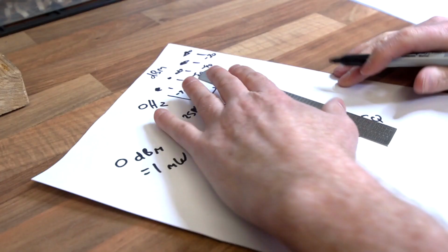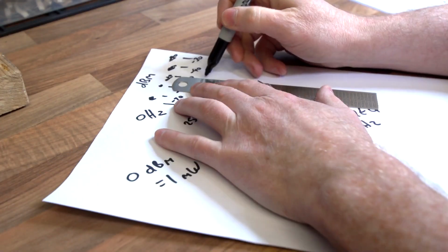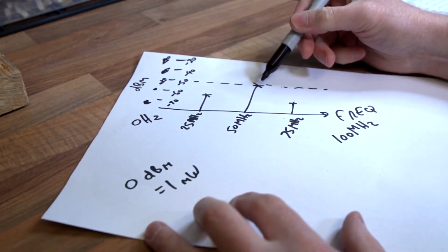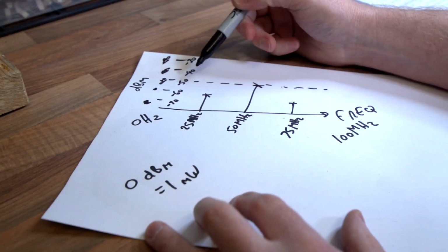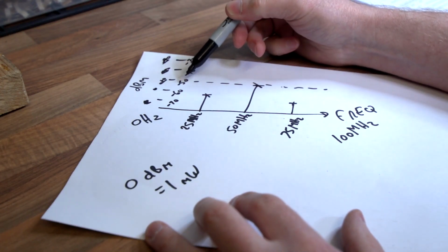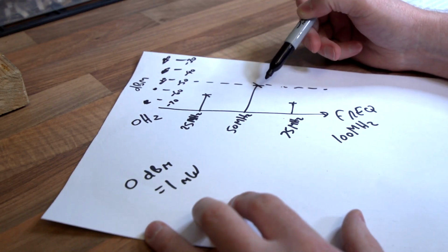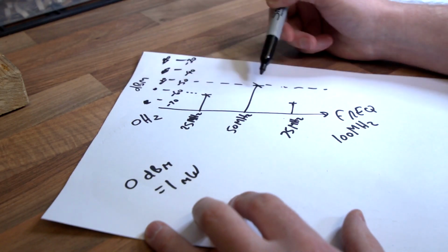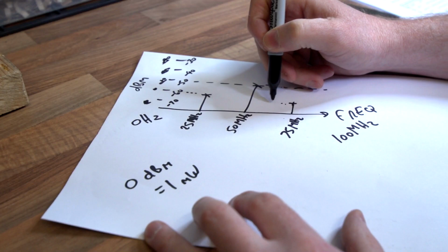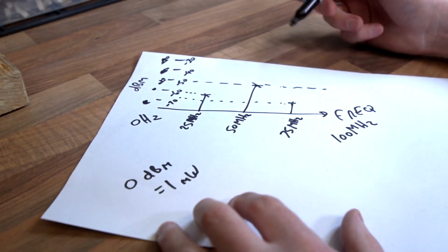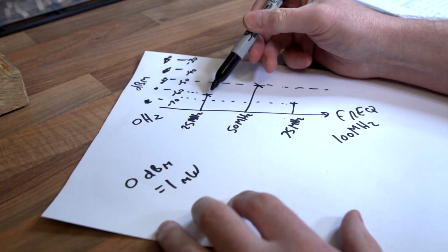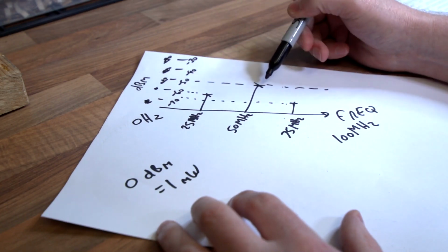So just get my ruler. If we take this signal here, okay, and we say, this point here, how high is it? And basically we're looking at -50 dBm. So that's -50 dBm of amplitude signal for this particular carrier. What about this one? Well, that looks about -60 dBm. That's smaller than that one. And what's this one? It's a bit messy. That's about -65. So you could say -65 dBm, -60 dBm, that's getting bigger, and -50 dBm.